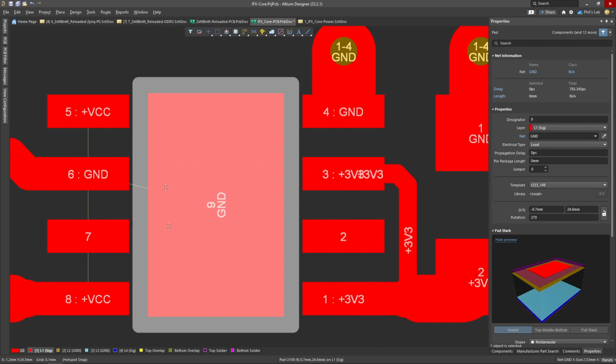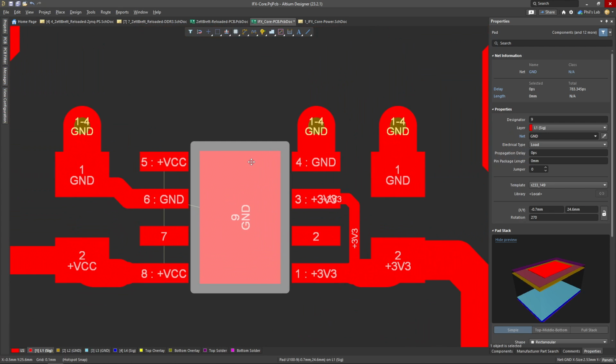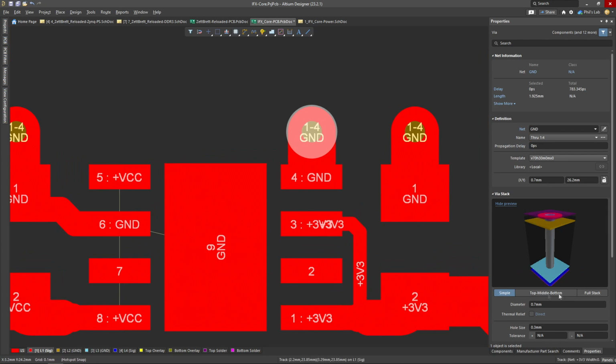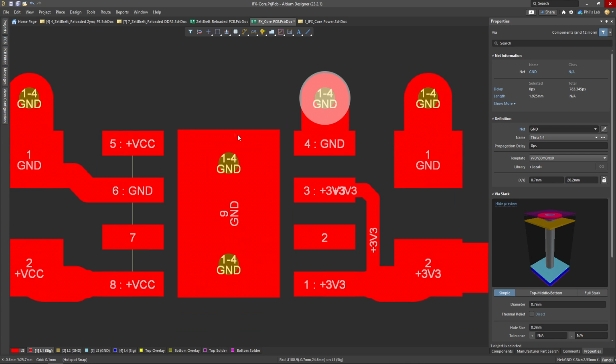We are still missing this exposed pad in the center, and we will need to place thermal vias in there, again, to wick away the heat that's being lost due to the series element of our LDO regulator. The vias I placed earlier were 0.7mm pad and 0.3mm drill. If I place those vias, for example, directly like so, we'll get problems with assembly because we'll have paste applied to this pad and these vias can then wick it away. We need to have the vias directly in the pad though, and directly down from the package, because this gives us the maximum benefit of using thermal vias.